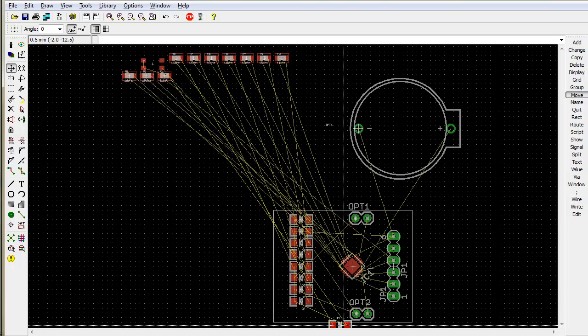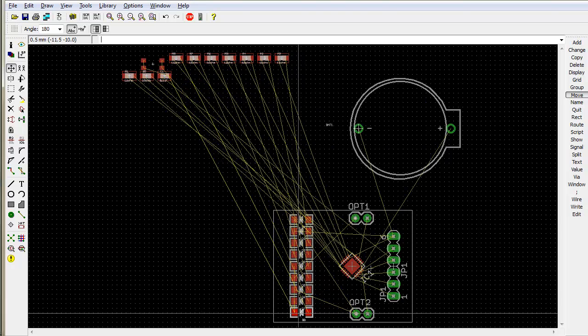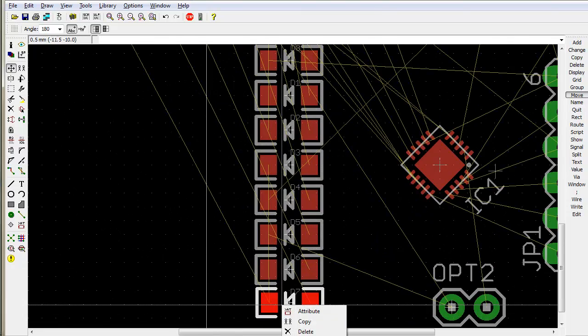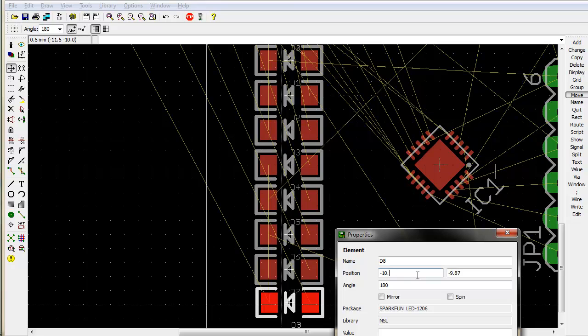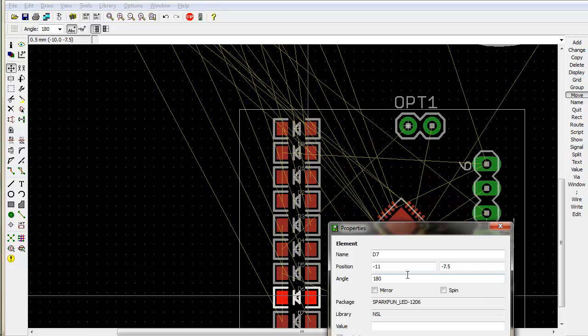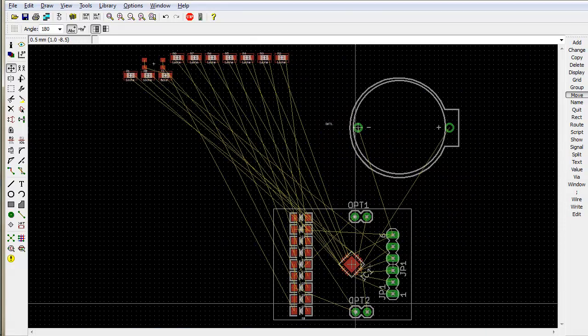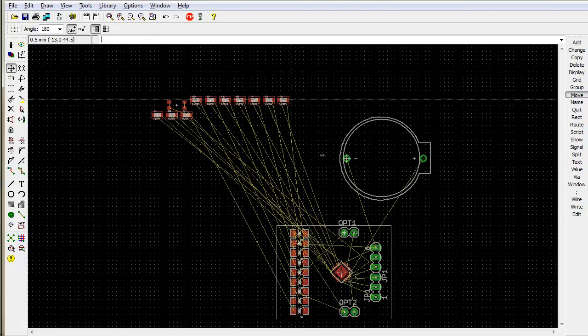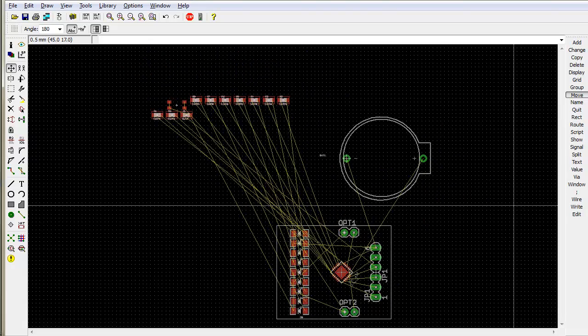And that's better. Now we can pick up this remaining one, which is the one that has been making me think, why on earth haven't they all lined up correctly? This one is not on an even, because we are switching between metric and inches. So that's why this is happening. That's why you don't do it. There we go. Let's put it on there. Let's check that one. Yep, so that one's good. Okay, so the reason that last one didn't go in the right place is because I moved it back with the mouse instead of actually going into properties and doing it.